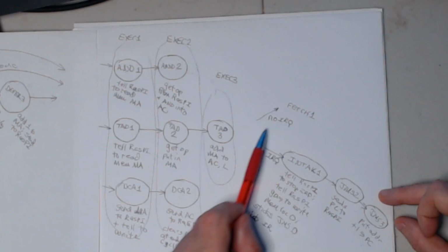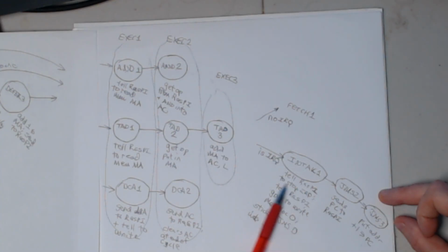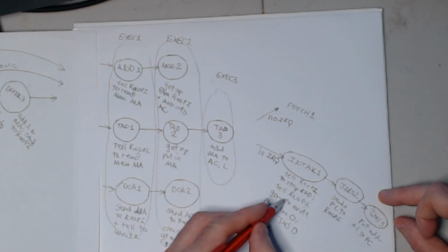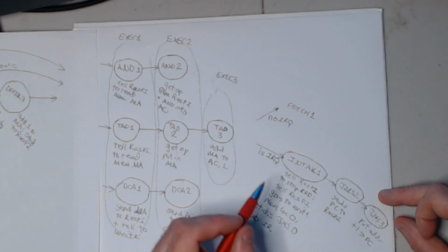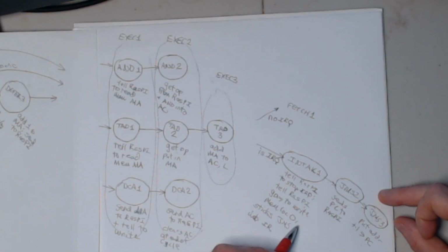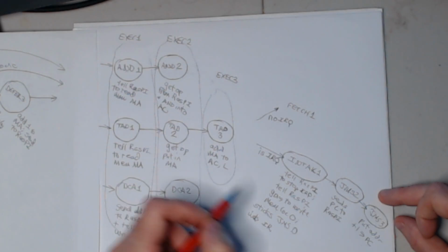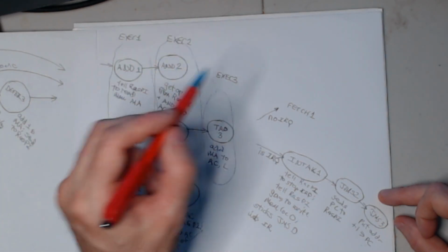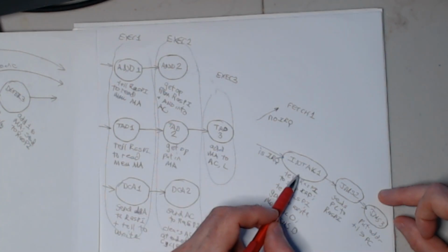That's either triggered at the end of instruction if there's an interrupt request, by telling the Raspberry Pi to stop requesting interrupts, and then store the program, or tell it we're going to write memory location 0, and sticks a JMS instruction in the instruction register. I think it's opcode 4000. So if you stop the tubes at this point, you should see a 4 on the panels in the instruction register, because 4 is the opcode for JMS.